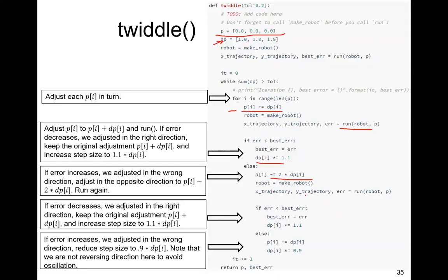So for me, it seems a little bit strange that you first set the P and then the I and then the D, because afterwards, if you add the differential part, then you can increase the proportional part. So they are kind of connected, those parameters. But maybe I misunderstood this twiddle algorithm. For me, it looks like it sets the first one first, and then the second one, and then the third one.